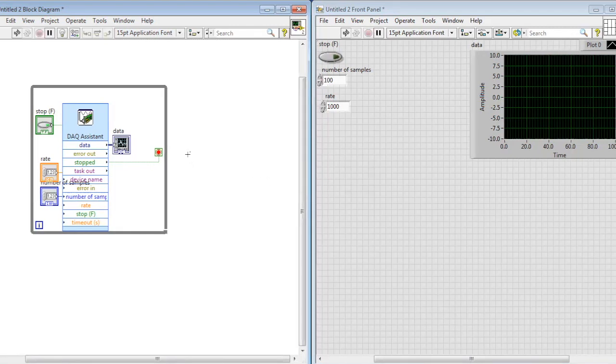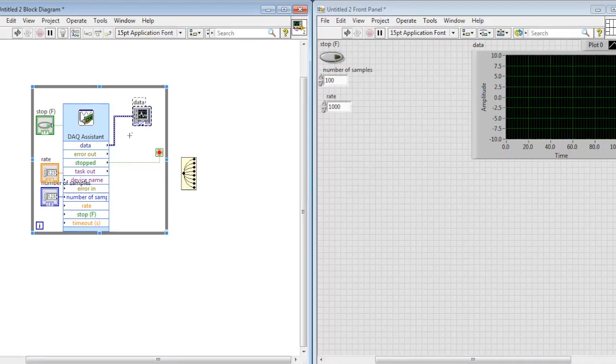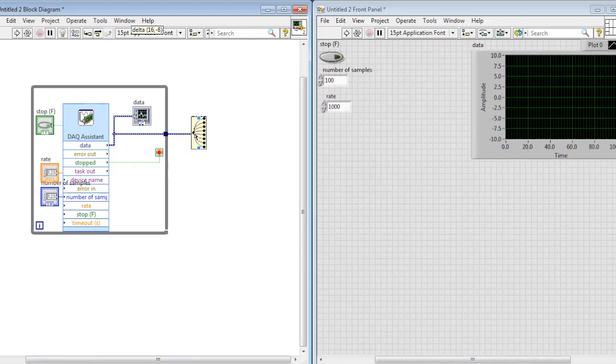We're going to expand that input to output ratio from 1 to 8. So the DAQ assistant is going to organize all of these signals that are coming into our DAQ. It's going to take all 8 of those signals and organize them through this split. So we're going to take that output from our DAQ assistant, and we're going to connect that output to the input of our split block. And as you can see, there's nothing on the right hand side of our split block.